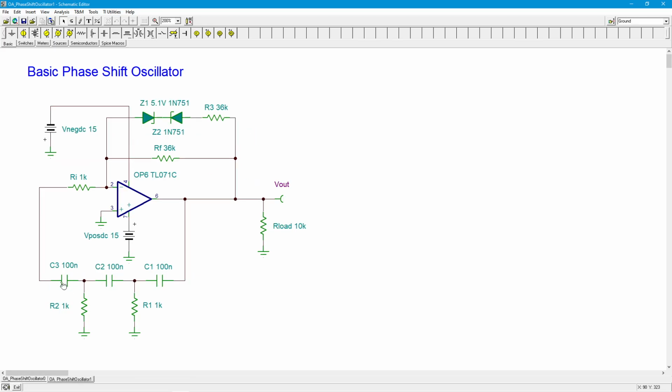Now, off of C3, we have this Ri. But this is going to virtual ground, right? That third resistor was going to ground, right? So it's the same. This is going to load these other elements just like the original circuit did. And ultimately, that current that flows through this Ri is the same current that would have flowed through the old R3 in the preceding circuit. So we can save ourselves a resistor. This kind of does double duty, all right? It takes that voltage, turns it into the current that feeds the op amp, and off we go.